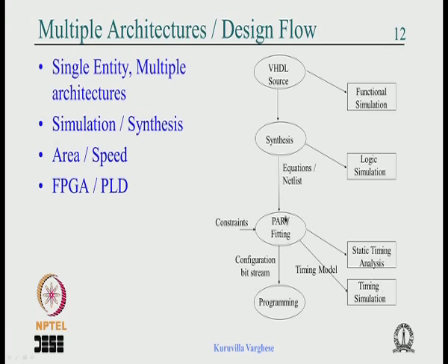timing simulation. Suppose you do the power and you do static timing analysis, then it is satisfied, then you can go for timing simulation. Maybe you have to iterate in all these steps and at the end you can program it. So that is the design methodology of an FPGA with VHDL as a source, and for that you have an editor, you have a synthesis tool, you have a place and route or fitting tool, you have a constraint editor, you have a static timing analysis tool, you have a programming tool and you have a simulator which does the functional simulation, logic simulation and the timing simulation.